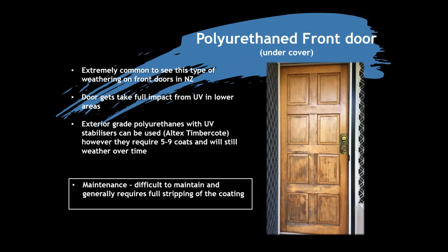The other thing is when they're being used in a marine environment, for say a timber yacht or motorboat, people forget that those types of boats come out of the water every year or two and they're maintained, and there's a lot of maintenance that goes on. Anyone that's listening today that's got a boat understands the kind of maintenance that's required. So we all forget about that. We put that same kind of polyurethane on a door like this and then leave it for 5 years, 7 years, and you're going to end up with what you see on screen.